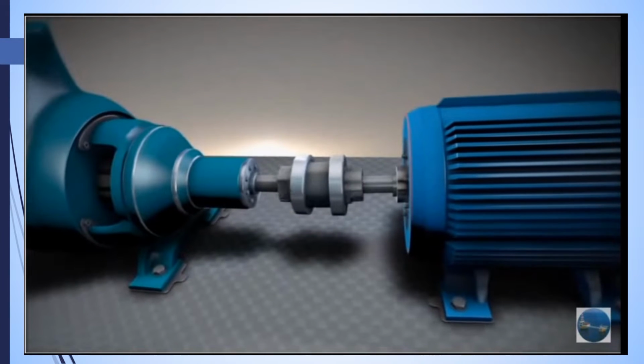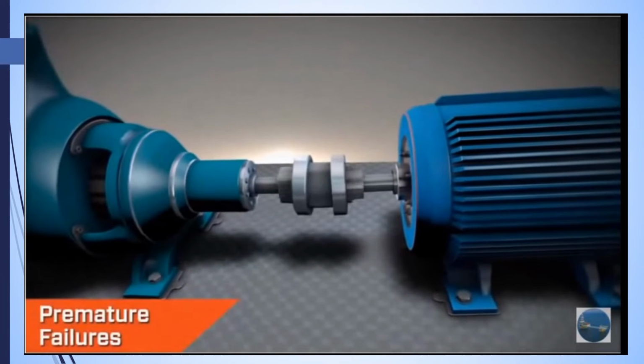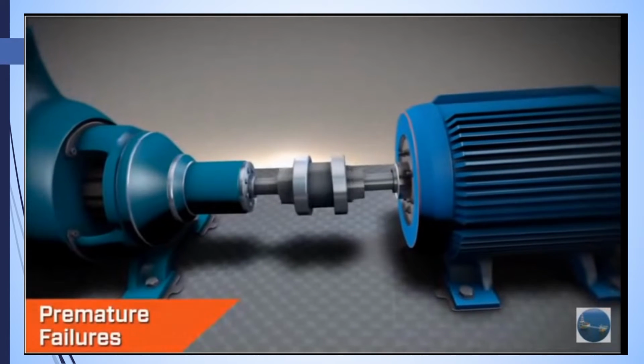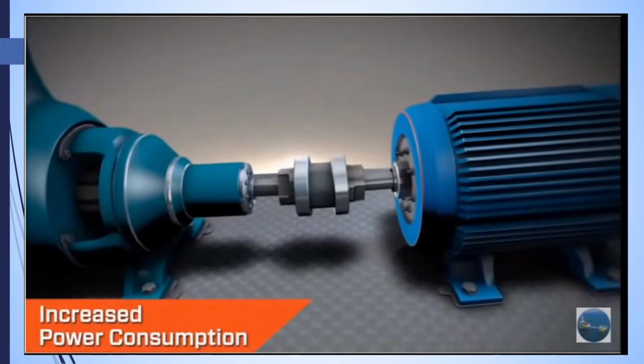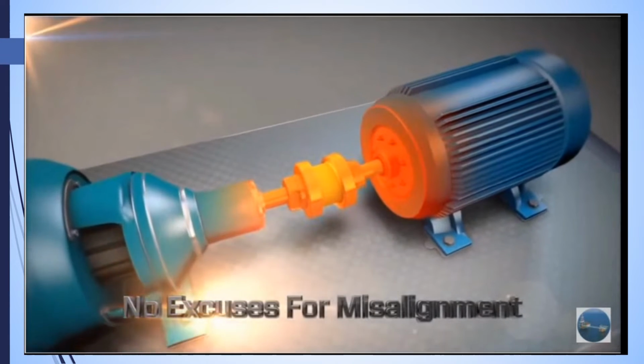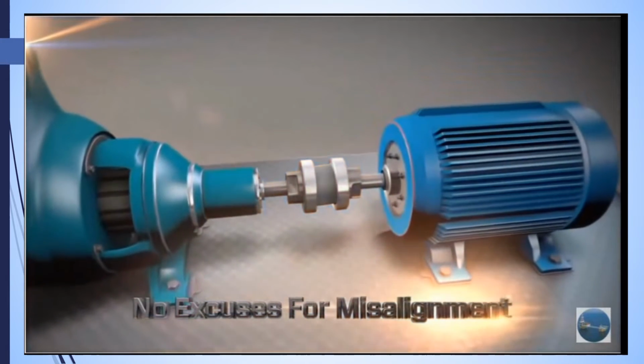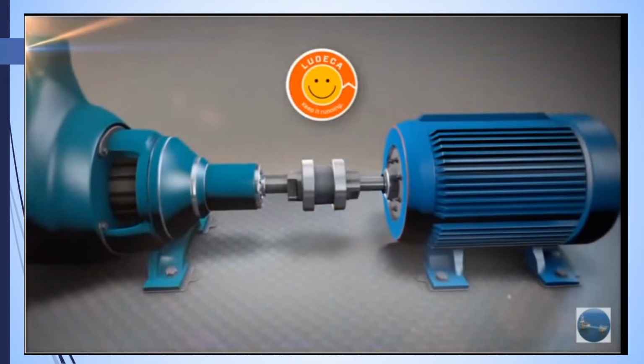The effects of misalignment are high vibration, premature equipment failures, increased power consumption, and reduced production. There's no excuse to let misalignment cost you money. Protect your machines and minimize costly downtime with precision laser shaft alignment.